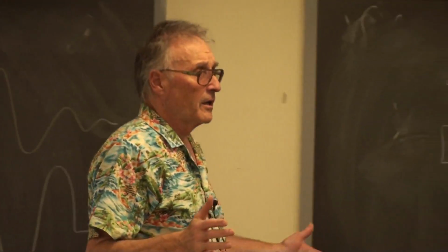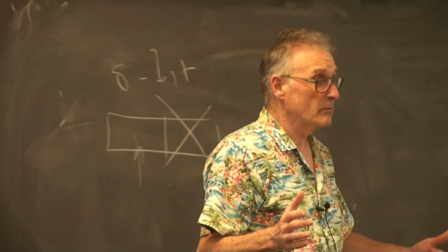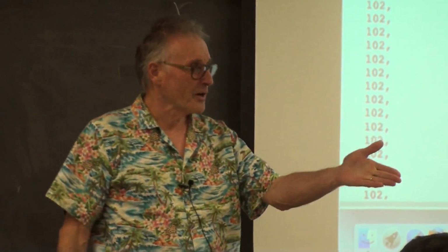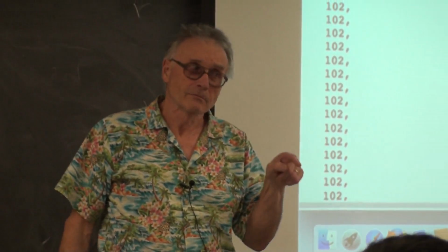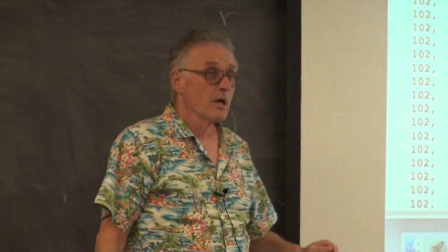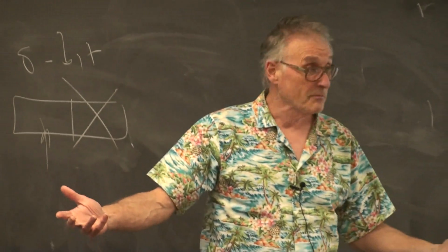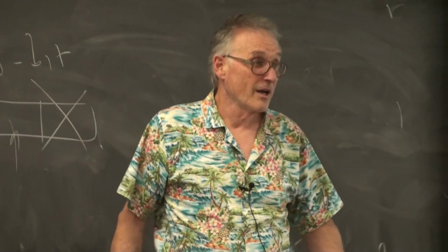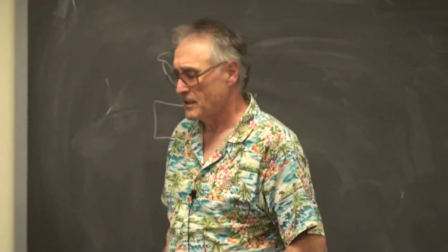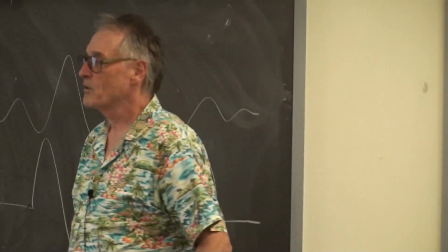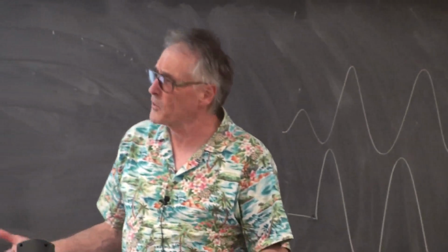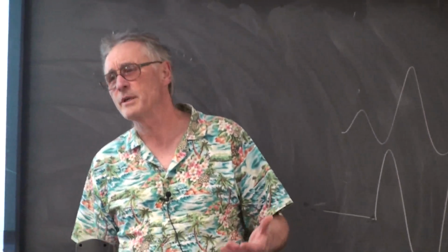So you can put a pretty big array. If you speak the numbers really fast, 1, 2, 3, 4, 5, 6, 7, 8, 9, 0, then first of all, you don't have to worry about interrupting the digit because you can't press fast enough to have to worry about concurrency. Secondly, it takes less flash. So if you record your voice counting at high speed, or find a synthesizer that'll do that, you can cut down the flash requirements. Maybe you can just avoid the compression altogether and get really good sounding speech out.